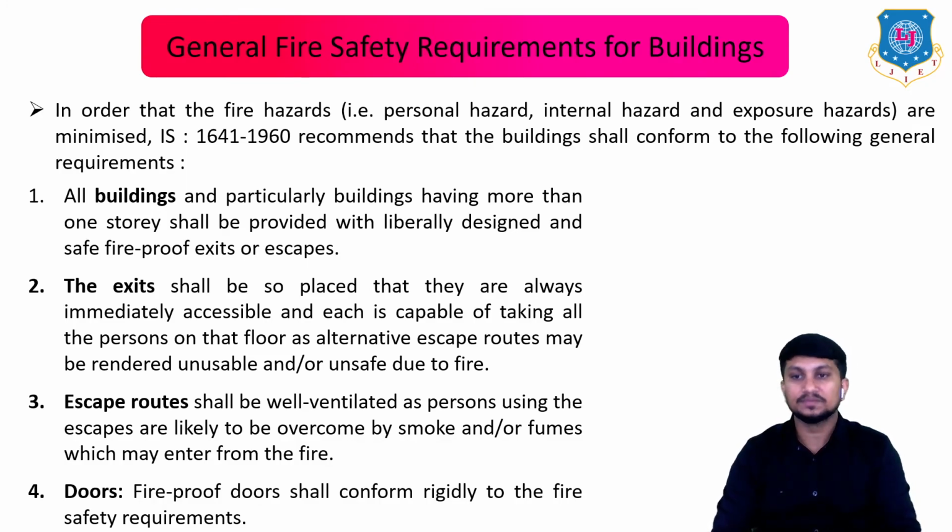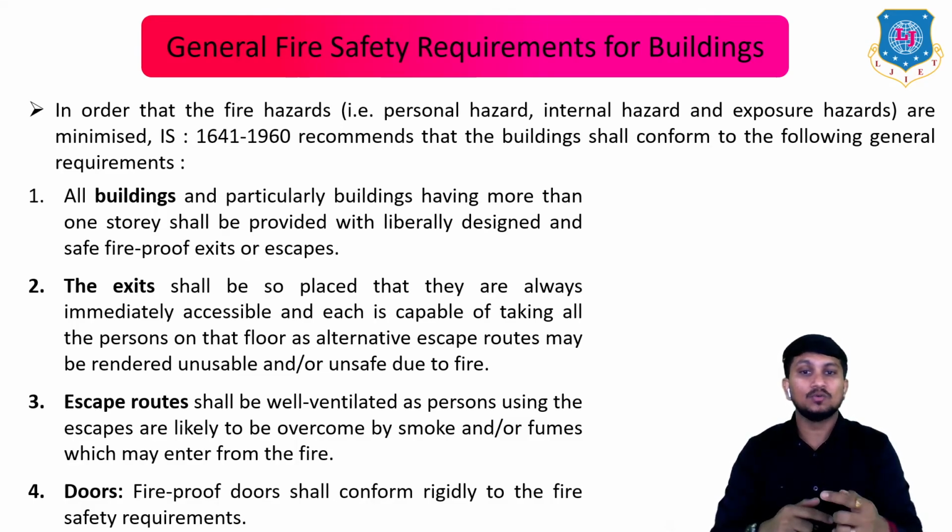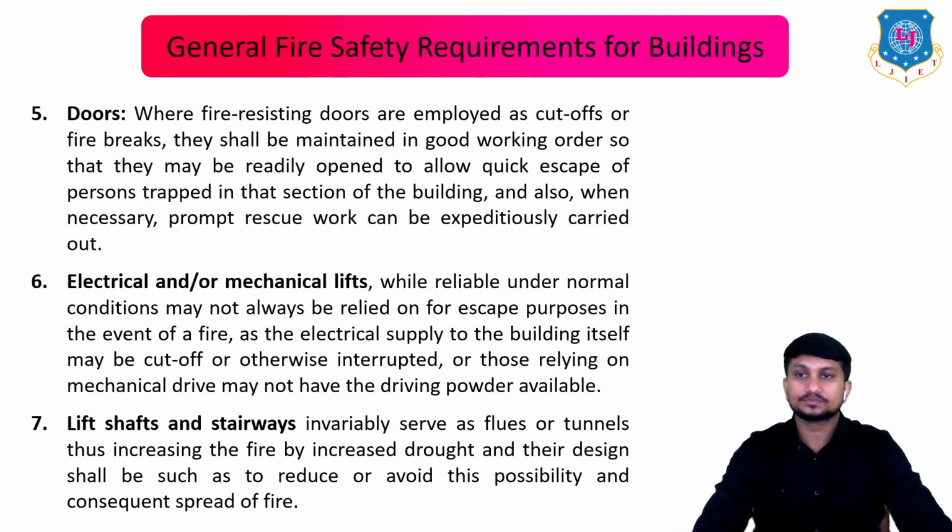Third is escape routes. Escape routes should be well ventilated as persons using the escapes are likely to be overcome by smoke or fumes which may enter from the fire. Okay. Fourth, doors. Fireproof doors shall conform rigidly to the fire safety requirements. Okay, the doors should be fireproof.